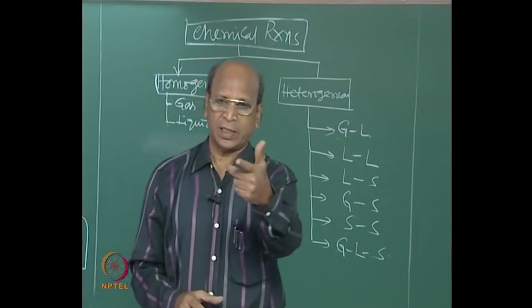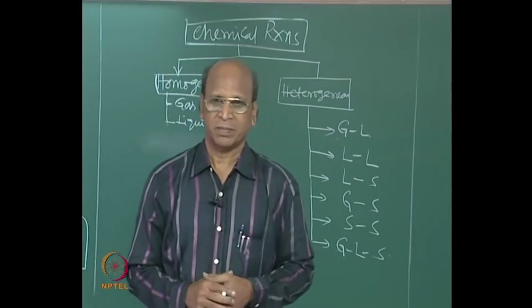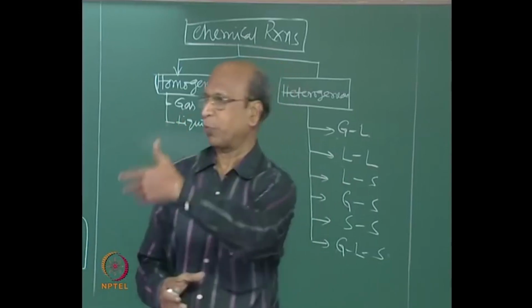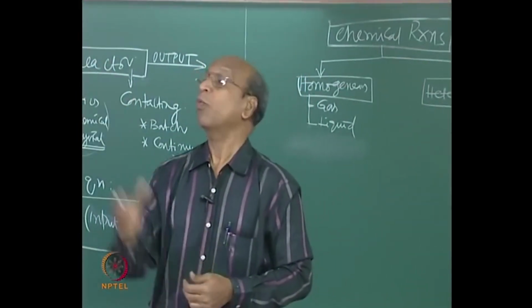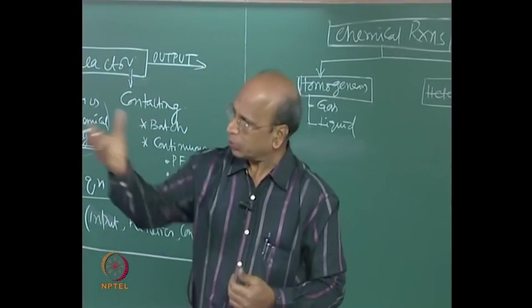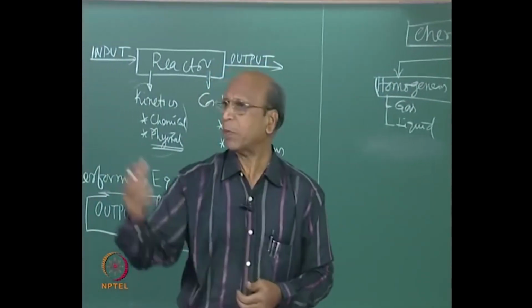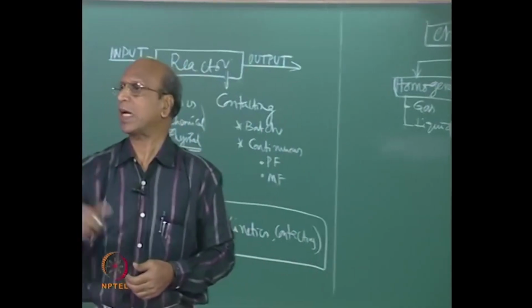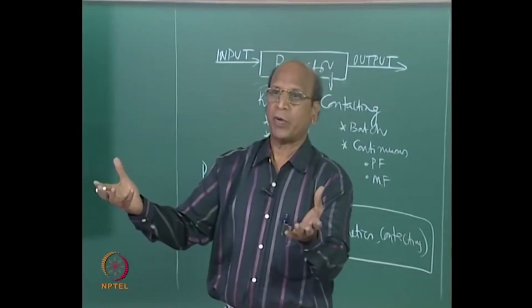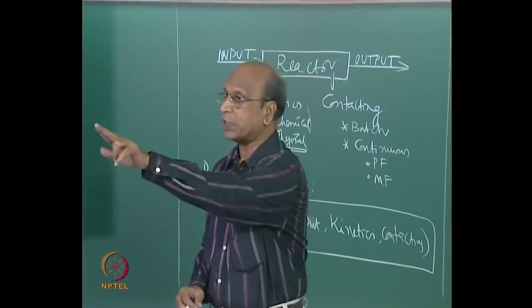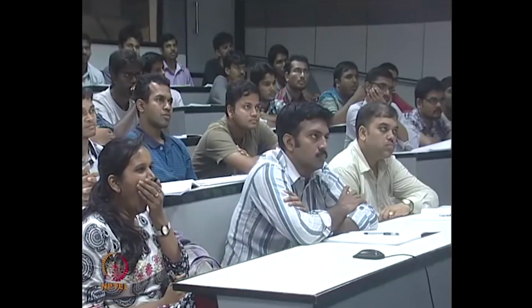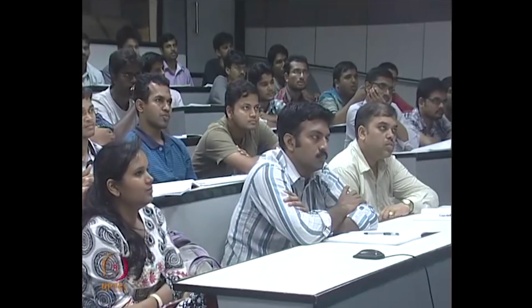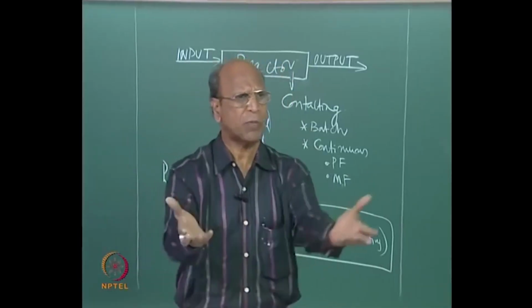You should have seen the design of catalytic reactors, right? So, definitely some of you. So, then what is the rate? How do they express the rate? Weight of catalyst. Is it the only way? Need not be. You can express surface area of the catalyst, but again it is very difficult to find out surface area, because there are 2 surface areas for a catalyst. What are the 2 surface areas? One is the external, the other one is all together, external plus internal together. Which surface area are you talking about?